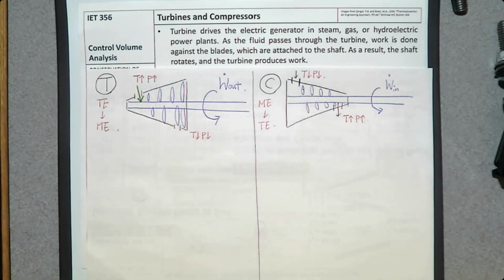So we provide mechanical work to increase the temperature and pressure of the working gas. When the temperature and pressure of the working gas go up, what does it mean? Its thermal energy goes up. So in the turbine, the high pressure, high temperature steam creates shaft power. In the compressor, shaft power is given to pressurize the system.